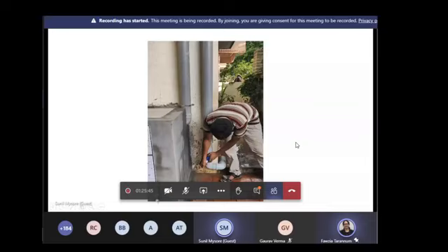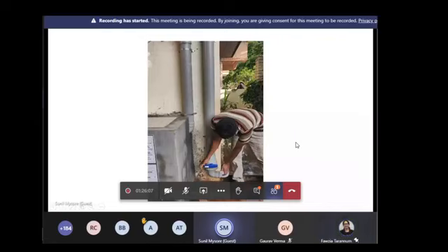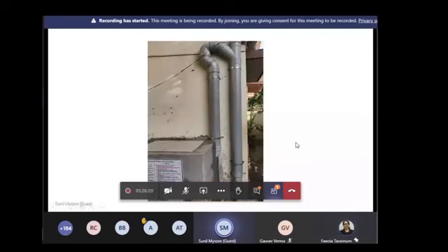So you see, when you open the valve, the water goes out. Every time it rains, after the rain stops, you have to open it manually, or you can have an automatic arrangement as well. But this is the valve which is used to throw out the water. When you close it, the water builds up in this water column, and then the overflow gets into the filter. So the first minute of water comes in this pipe. And see, this is the Y joint to take care of filtration forces. There is no T joint. Since it's a Y, the water essentially has to flow.